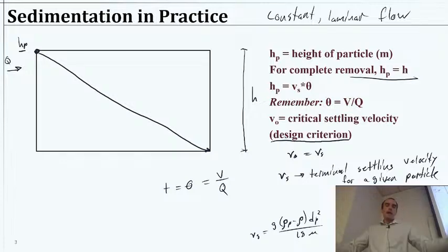But, okay, if we have some space and we have to treat some flow rate, then how good can we do before we need to just say, all right, let's keep it a little smaller, then let's treat with coagulation and have a second clarifier or second sedimentation basin. So it is a very good question. Usually about the size of particles, tens of micrometers are about the smallest we could do. And even those, usually we might expect to not get all of them, so maybe 20 to 50 micrometer particles would be typical.